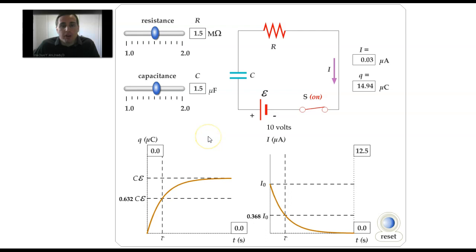Notice that this is what we call an RC circuit during charging. That is, when we close the switch, we allow the capacitor to be charged through this resistor. Now, by the way, typically this resistor is going to allow charge to be stored at a certain rate that we're interested in. So we could change the resistance, but for now, we're just going to charge the capacitor through the resistor. So the resistor helps to modulate how quickly charge is stored on this capacitor.